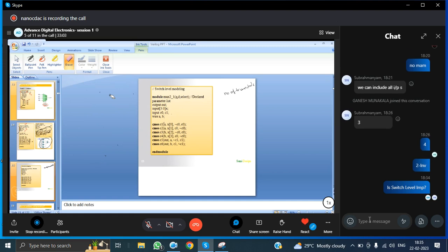Why? Because now, if you want to design a normal 8x1 multiplexer, a normal 8x1 multiplexer will take more hardware and consume more area, or an 8x1 mux using 4x1 multiplexers will consume more area. When you need to compare like that, only at switch level modeling can you analyze which circuit is occupying more area, more gates, more number of transistors.